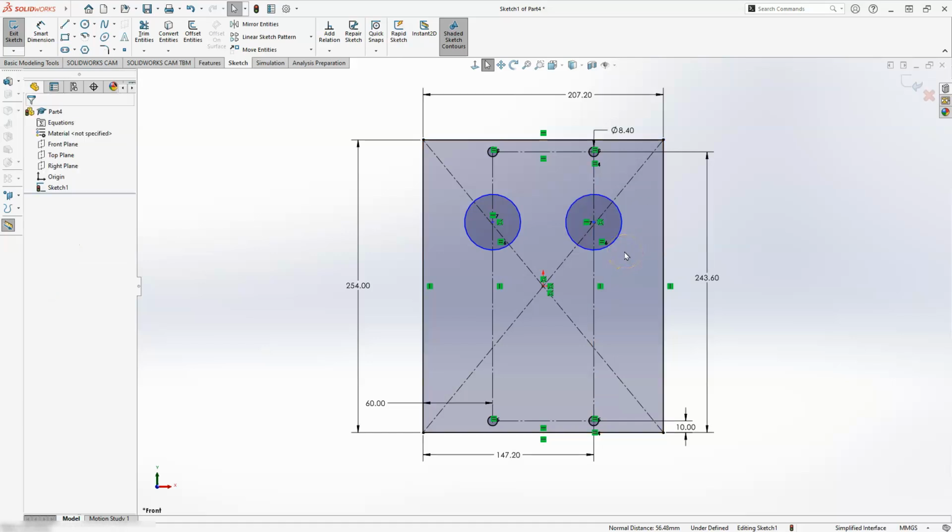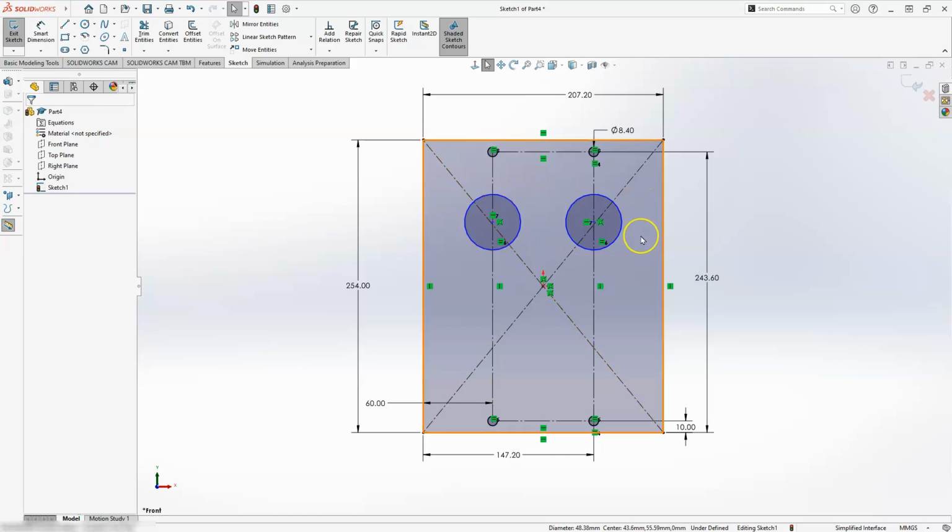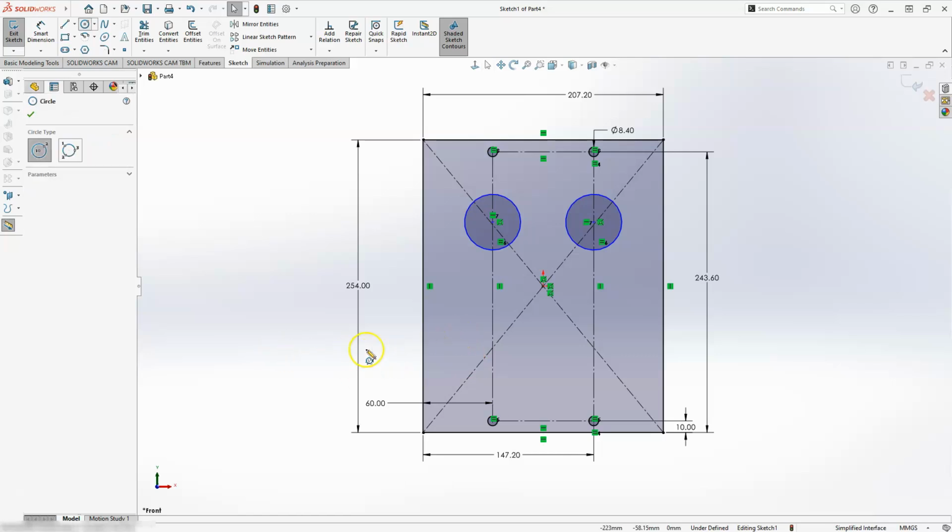Alright, so now from here, I can go ahead and select this line, or that circle. If I hold down the shift button, and remember, I already made those two equal. Oh, actually, I'm sorry, I got the two wrong holes here. I was meaning to make two holes on the outside, but that's okay. Let me go ahead and put two more holes on here. I think I'm a little bit ahead. So these two circles here have a diameter of 38.3. But let's go ahead and put the other ones on there just so we can go ahead and specify them.